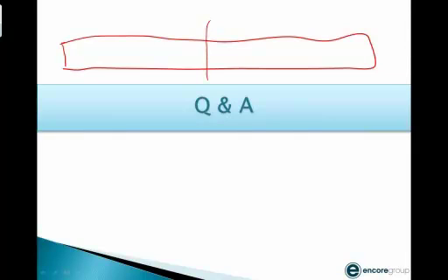In roadway construction, you're going to bring your excavation crews. They're going to be coming down, getting your grade, and then right behind that, your finishing crews come behind. They're getting compaction. Then you're doing your base course, and then you're doing your paving. So you have a flow of your crews that you plan. This is a simple example, and you're moving down through here. Let's just take your excavate and grade. You're getting, let's say, 200 units per hour, or 2,000 units per day, or whatever it might be.